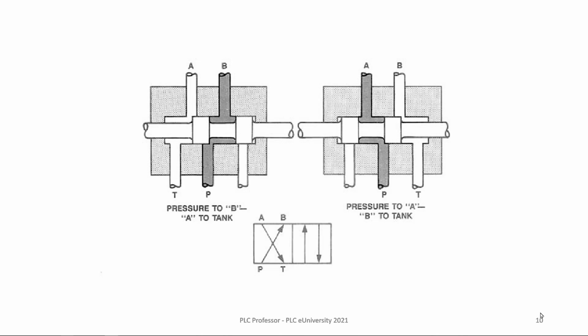So you see the spool is that rod traveling horizontal that has the two, if you want to, kind of reminds you of camshaft lobes, but they're not eccentrics. They're bored extremely close tolerance. As a matter of fact, some of these pneumatic valves have O-rings to seal those lobes on the spool. Some of them have a micro finish, meaning that the tolerance is so close that it's metal to metal when the spool is shifting.